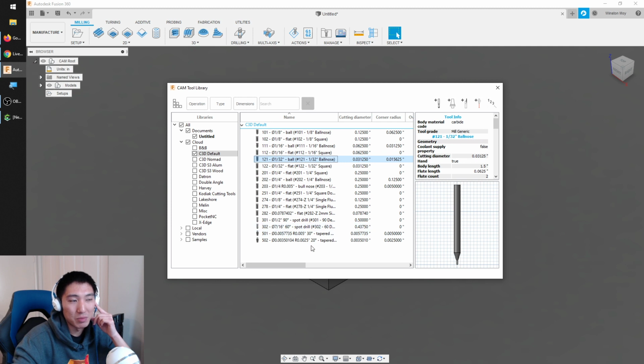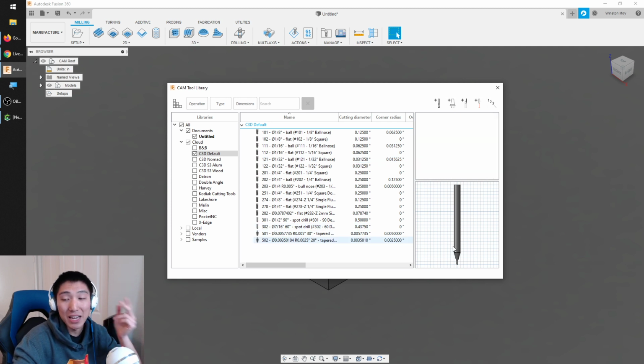But it's going to be something you're going to have to feel out. Take notes when you're machining. See what works for you, what doesn't work for you. If you're cutting something, if you think you can go faster, try bumping up the feed rate override. See if you can push it a little harder. If so, when you go back to your computer, change your speeds and feeds, change your recipe. It's a continuous learning process.